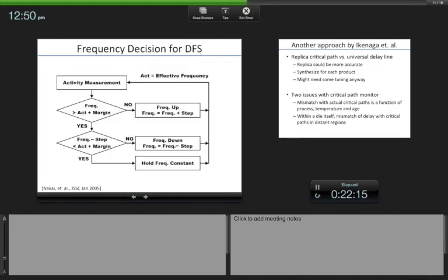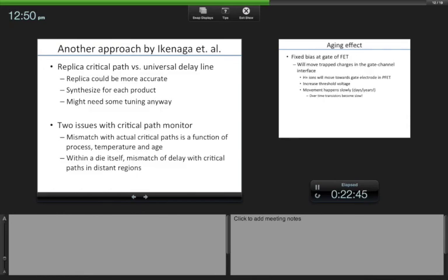Because how do you adjust the frequency? There are two ways. You can just change the division factor. You have a fixed frequency source and you just change the division factor. But that only allows you to get coarse steps, f by 2, f by 3, f by 4, etc. But if you want frequencies in between, then you have to adjust the PLL, right? So then the PLL frequency itself changes. But no matter what, there will always be a fixed reference coming in with an external crystal and so on. So you can use that to derive your fixed frequency clock.